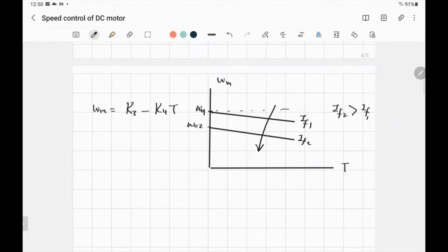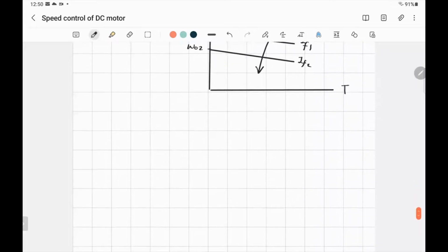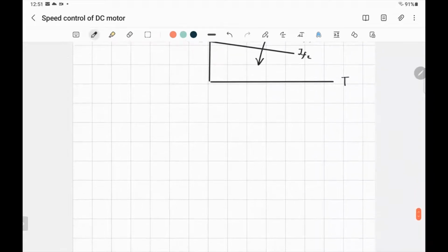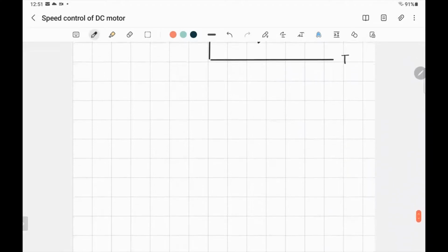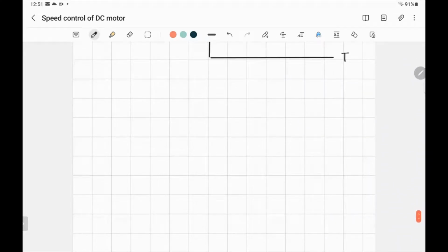I'd like to talk about field control a little bit, because it's practical, they actually use it in real life. When we control a load, we usually start control from 0 till it reaches the nominal speed, usually by armature voltage control. So if you have the machine, you want to reach the nominal speed. Let's say the nominal speed is 1200 RPM, like what we have in the lab. So how will we control that? You have load, and you start increasing the voltage gradually from 0 up, let's say 120 volts was the rated value, till we reach 1200 RPM.